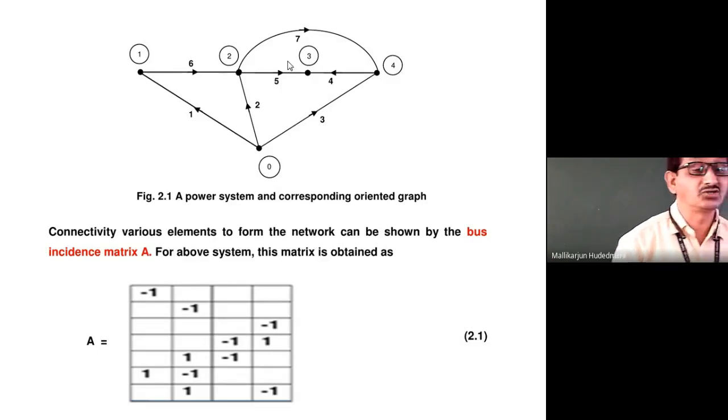Now you have witnessed the problem I have taken. I assume all the elements possess admittance. The elemental admittance of element number 1 in this diagram is Y11. Element 6 possesses Y66, element 5 possesses Y55. Like that, each element possesses an elemental admittance. They are the ones I am going to use in the Y primitive matrix. So the A matrix of the problem must be formed. A transpose is quite easy: change the rows to columns.